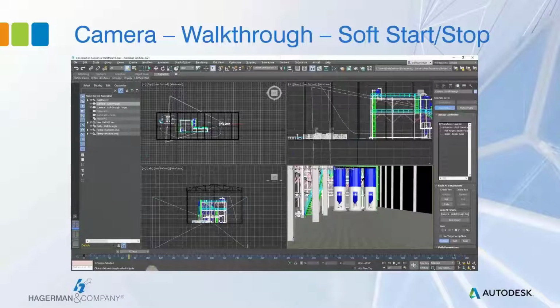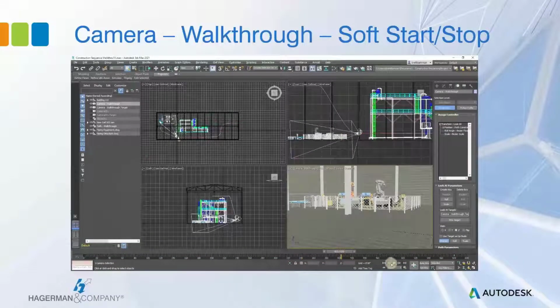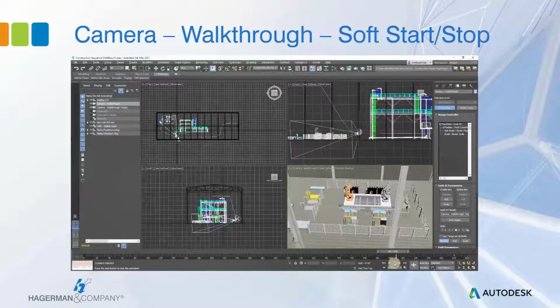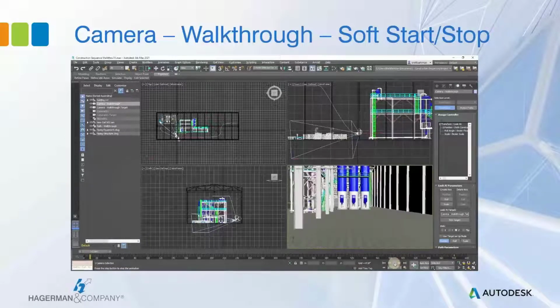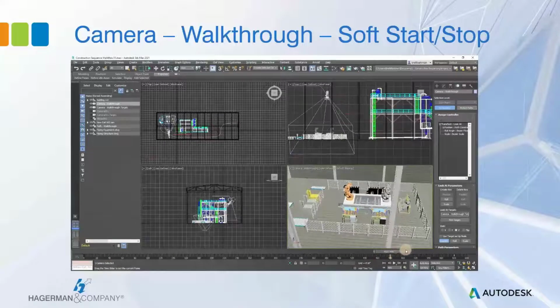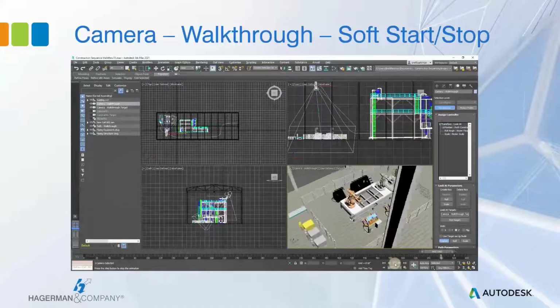Now, to get a real good look at how it is stopping, we'll pull that last key back so the movement ends before the end of the timeline, and you'll be able to really see that it's moving, and then all of a sudden it's not moving. It's a very distinct stop, not very realistic. And that's what we're going to change next. The tool we're going to use to do that is called the Curve Editor.